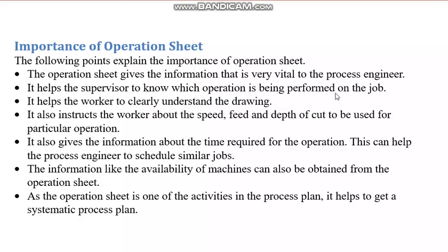Okay, the operation sheet will tell the supervisor which operation is being performed. See, drawing alone will not show. Drawing will show this is how it should be looking finally when the machining is done. Okay, but the operation sheet will tell the supervisor which operations are going to be performed on the job.